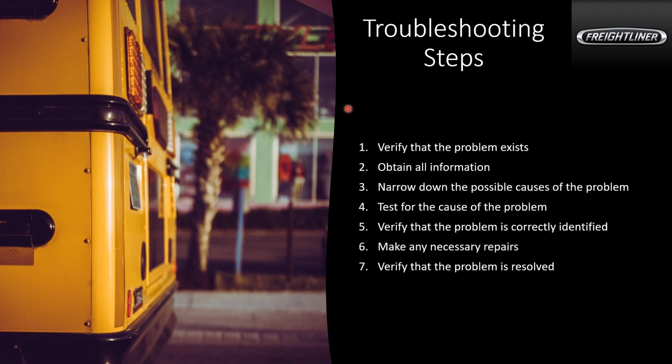The very first thing is going to be kind of obvious, but it's very important, and that's to verify that the problem exists. A lot of drivers just don't know how to use systems or don't understand how to use a new system. So it's very important that you actually verify that the problem exists. We don't want to troubleshoot something that is already working. And the other reason why this is very important is because sometimes problems are intermittent. Sometimes they work, sometimes they don't work. So it's very important for you to verify that there actually is a problem, because if there's no problem at the time, it becomes very difficult to troubleshoot any system when the problem is not there. So verify that the problem exists.